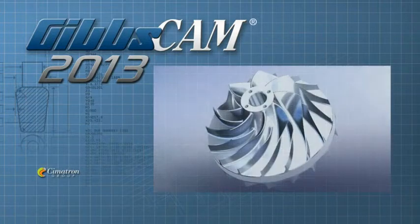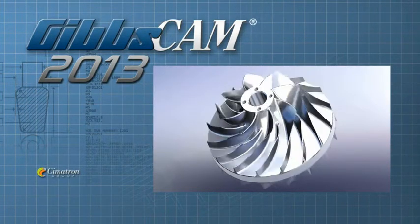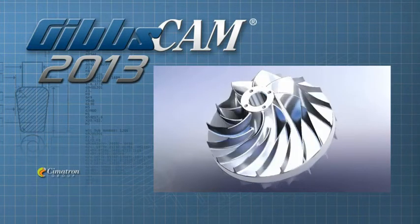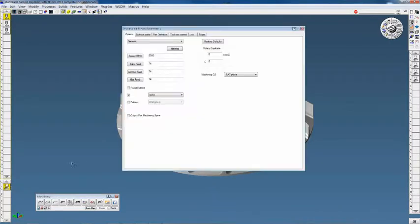Machining of impellers and other rotary bladed parts requires some of the most complex and challenging 5-axis programming efforts. The GibbsCam 5-axis multi-blade option was developed to simplify the programming of multi-bladed parts. Creating a new multi-blade operation is the same as creating any other 5-axis operation, by starting a new 5-axis process.